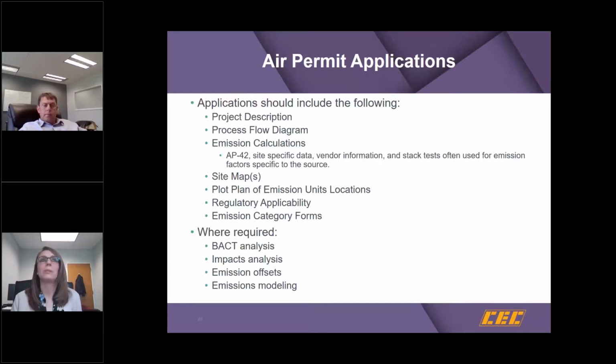And we can do that in a wide variety of areas. Sometimes we use programs called TANKS to model tank emissions, or we use ProMax a lot in our office dealing with oil and gas, and that's a good way to model emissions as well. Yeah, the emission offsets, if you're Title V or below, minor source or synthetic minor, you're not going to have to worry about emission offsets. That's really your PSD level facilities that are dealing with all that stuff.